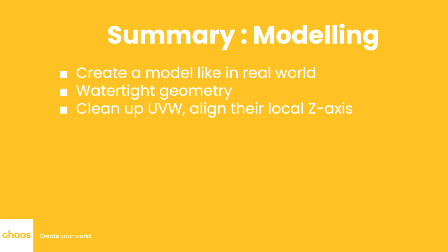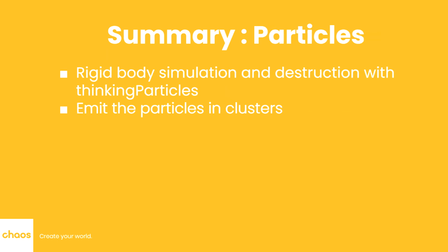In conclusion to this video, I demonstrated how to create convincing pyro effects using Phoenix and thinkingParticles. I built the model as if I was constructing it in the real world, making sure the geometry was a watertight model with clean UVW mapping and aligned the local z-axis for the wood planks. For the rigid body simulation and destruction, we used thinkingParticles. When generating particles for the Phoenix source, make sure they form clustered formations.